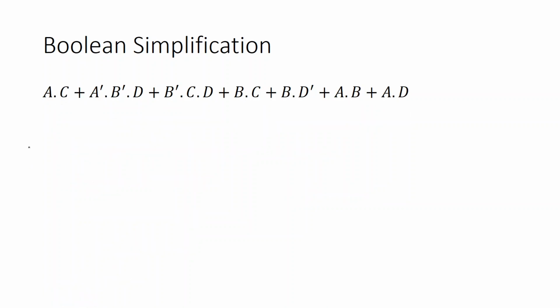Another one we will do very quickly, and here there are no brackets to be opened. So what we would do, we would first look for the consensus theorem, if the consensus theorem could be applied. So consensus theorem means that I would look for terms where I have the one term and another dash term and another term where the other two terms are combined together.